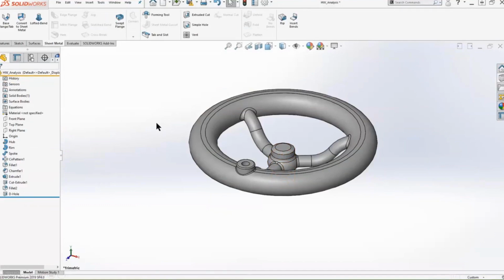So it's really the best way to rebuild a part, in my opinion, but do understand if it is a very complex part, hundreds of features, it's going to take a while to rebuild. So, use it wisely. They always like to say, with great power comes great responsibility. Control Q rebuild, very, very useful. Again, it'll take care of any kind of issue that you potentially have rebuilding your tree.